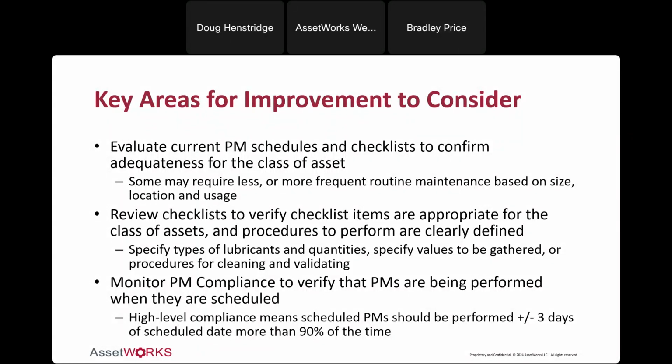So you want to make sure you're revisiting your inspection checklists as you bring in new pieces of equipment, new assets, because things change. The way units are constructed changes, and you often can use the OEM recommendations as a good guide that you may have to diversify the schedule and the checklist process a little bit as you go.